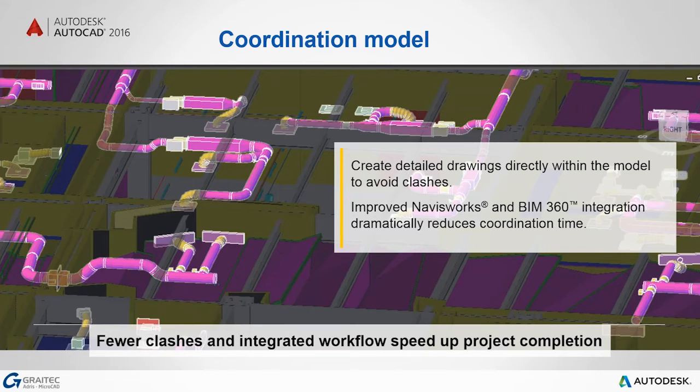If you're not familiar with that, it's a superb coordination tool. It can literally bring in just about every single file format, CAD format you can imagine, and bring it into a coordinated file. So you can do error checking, you can start measuring off things, you can do clash detection, you can even generate little walkthroughs around scenes as well. So if you're not familiar with Navisworks, it's really worth a look if you're considering you want to do 3D and coordination of drawings from different CAD operating systems.